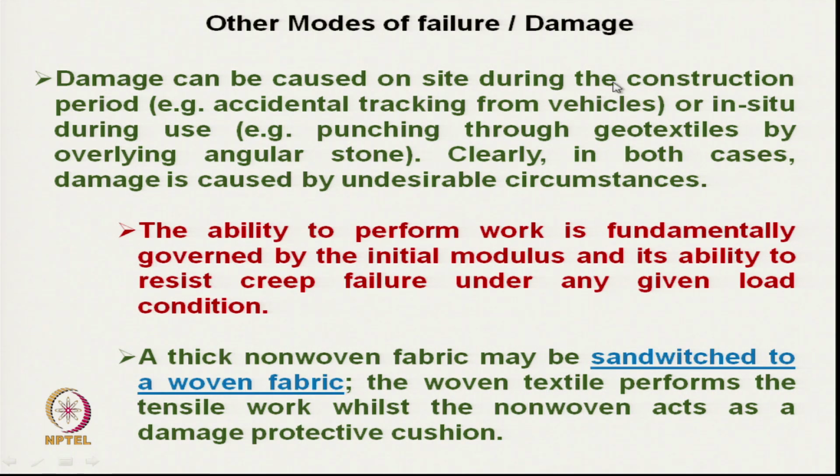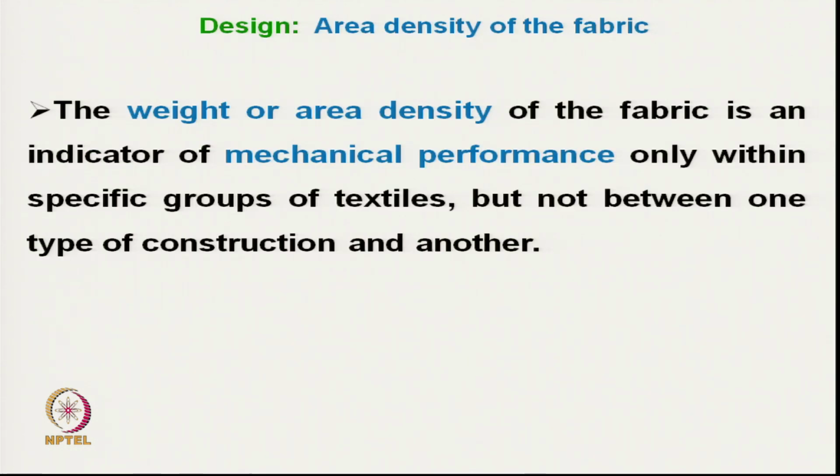So, due to this type of damages by punching by stones, if we want to protect woven fabric, at the upper level we can use non-woven which will have cushioning effect. Now, coming to design of geotextile.